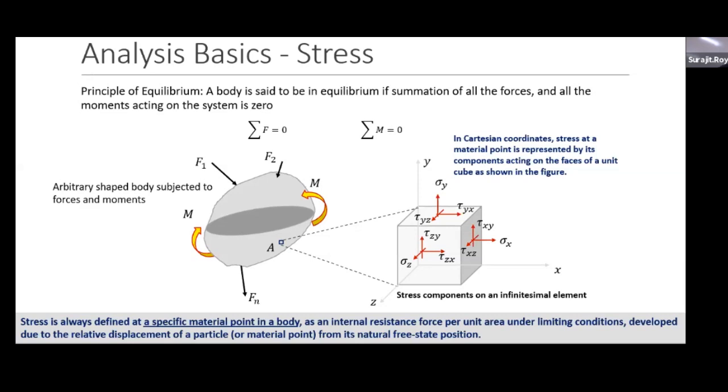And second, because of the heat treatment, there are residual stresses that come into the system. So you are not only relieving the stresses, but if your component is an assembly, not just one piece, then an assembly of the whole components is very difficult to heat treat, and then the residual stresses will come into the system. So that is the cons for that.